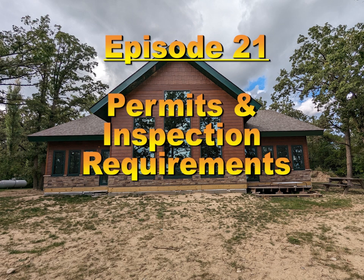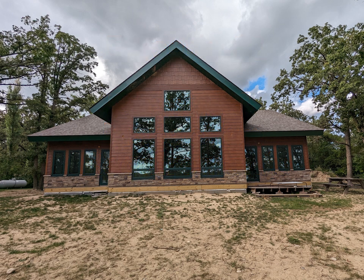Episode 21, Permits and Inspection Requirements. The number of permits and inspections that will be required for your building project varies greatly based on your state and county. Some jurisdictions inspect you every time you turn around, having inspections including items like shower pan drainage, plumbing rough-in, and others, culminating in a certificate of occupancy. Other jurisdictions aren't quite as stringent, which can be a double-edged sword.